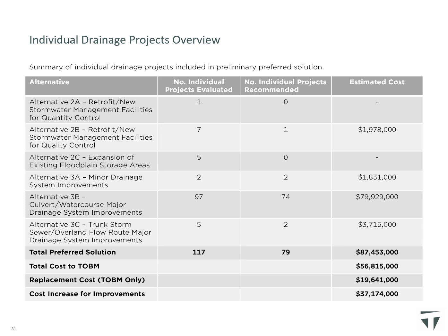Additionally, the town is considering completing calibration of the Drainage Master Plan models to improve model accuracy. The current models are conservative and produce higher than anticipated peak flows, and we anticipate that model calibration will result in reduced peak flows, allowing for smaller infrastructure to be constructed at reduced costs to the town.